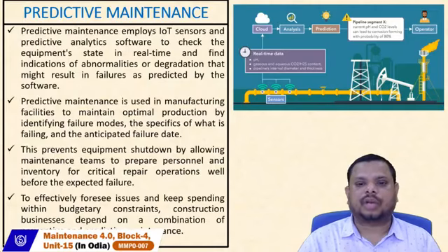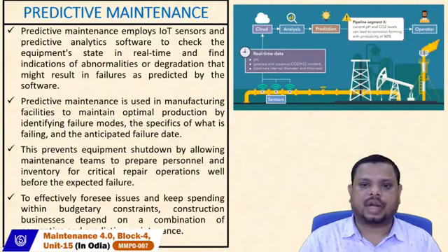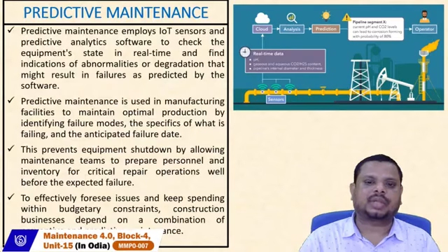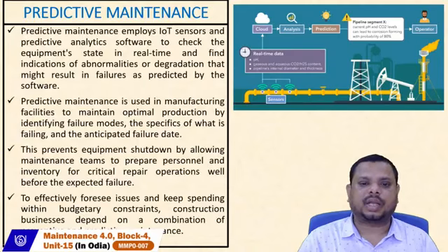So here, from this particular image of an oil and gas company or oil refinery, the pipelines are installed with a number of sensors, and these sensors are providing real data, that is the pH value of oil, gaseous and aqueous, that is CO2 and H2S contents. Then the pipelines' internal diameters and thickness data will be given by the sensors.